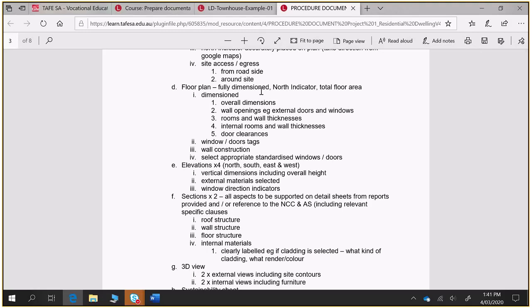I don't mind if you drop a couple dimensions in there to take some information out of the dimensions further out. That's fine. When you're dealing with something like this, it's got a whole lot going on in that centre bit. Sometimes it works for you to get some dimensions in their own separate place within that floor plan. That's okay. Typically you don't do that. You avoid doing that and you keep everything in your dimension lines around the edge of the building.